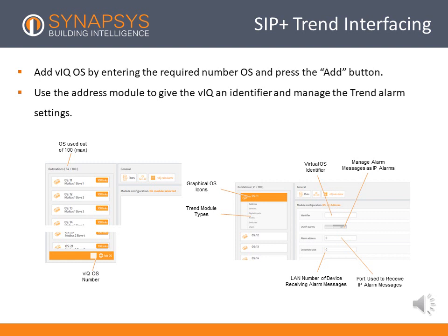Use the VIC Define Points page to create up to 100 outstations, using the column down the left side of the page. Add a unique outstation number between 1 and 119, ensuring that 2, 3, and 10 are not used, and press the Add button. The new outstation will appear and can be configured.